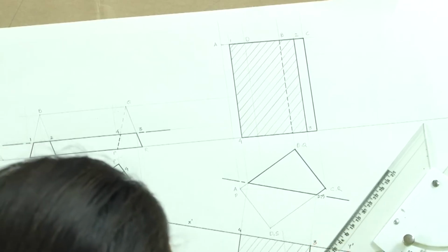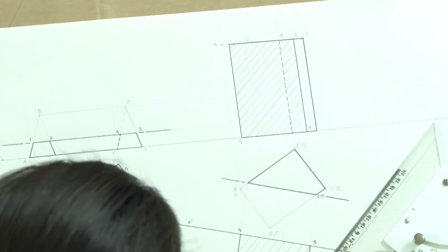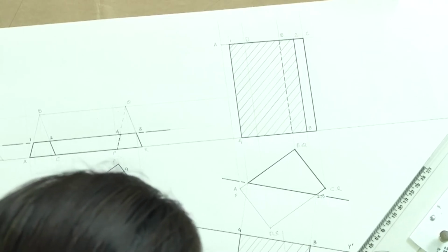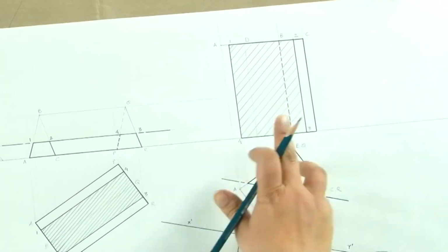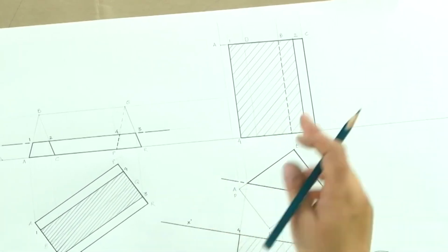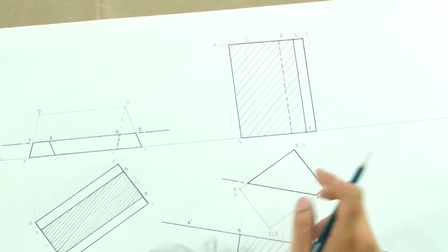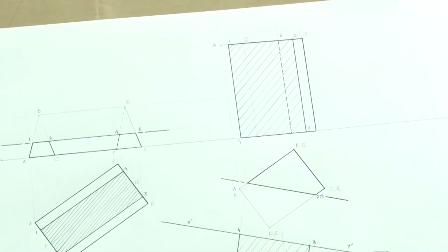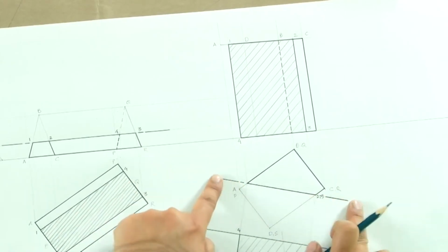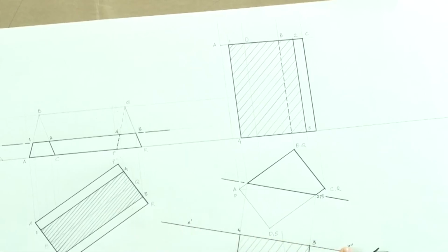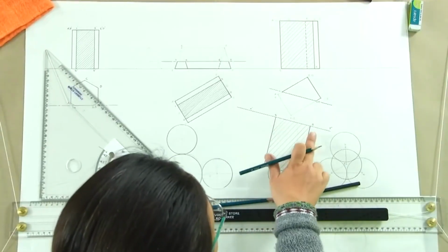If you see again, we had the section as a rectangle, because in this case also this section plane is parallel to the axis, and that is why we are going to be seeing the section as a rectangle, and the true shape of the section will be drawn on a plane parallel to the section plane. So, we will draw a new auxiliary plane and a new reference line X dash Y dash and project the true shape of the section onto this.